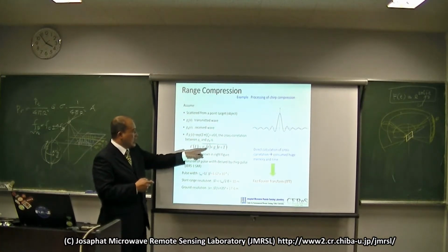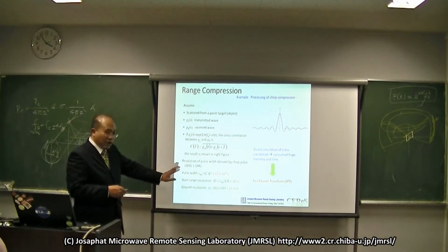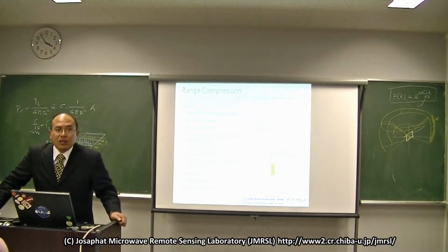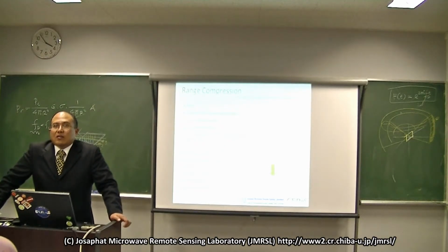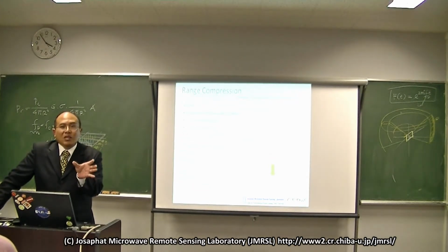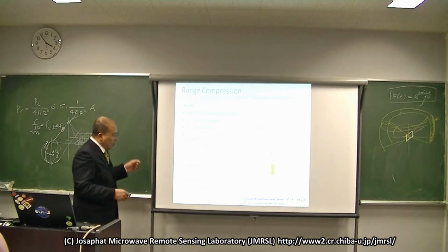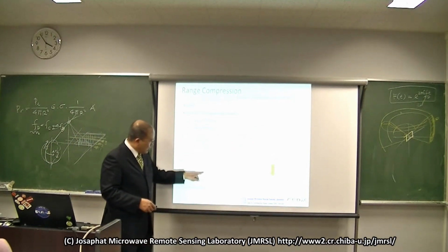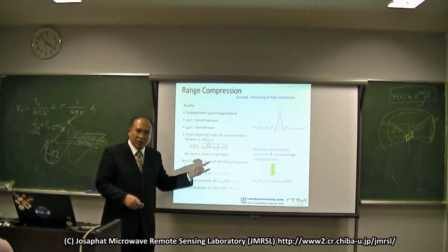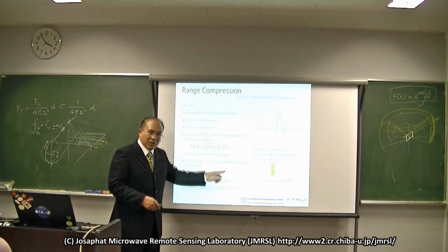It is the same in time domain. And then we compare with the last calculation. We use the chirp pulse, and we got that the ground resolution is 9 kilometers. The pulse width is 1 divided by delta f, and delta f we already know, it's 15 megahertz. You insert it there, and you can find it.